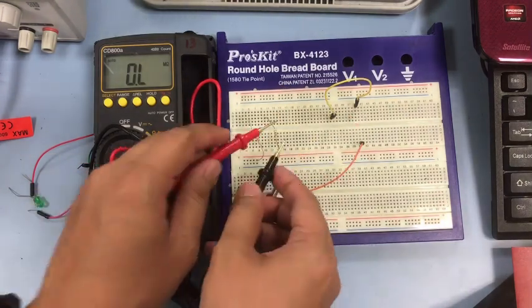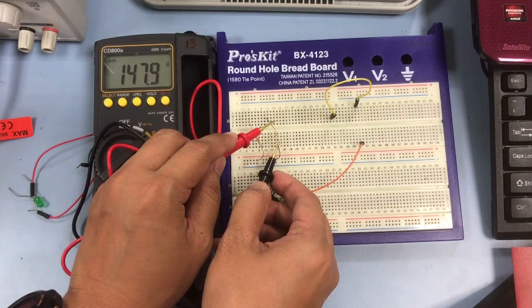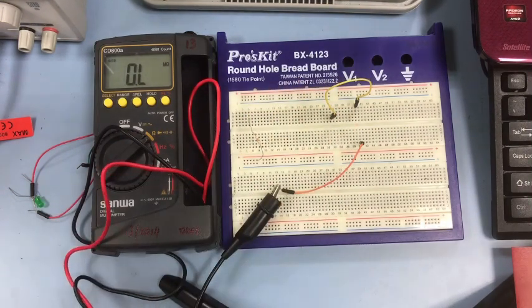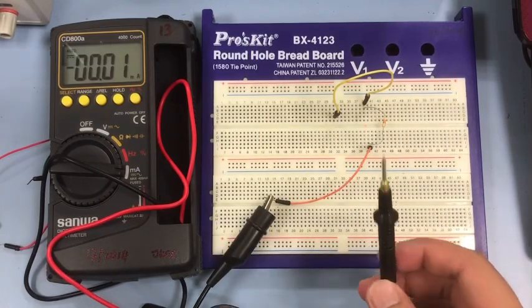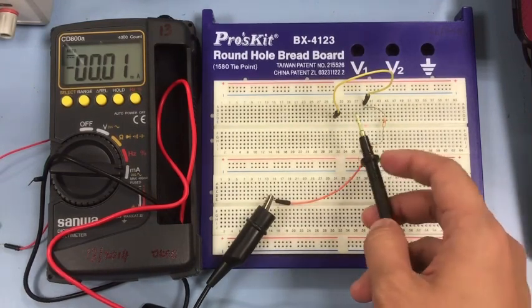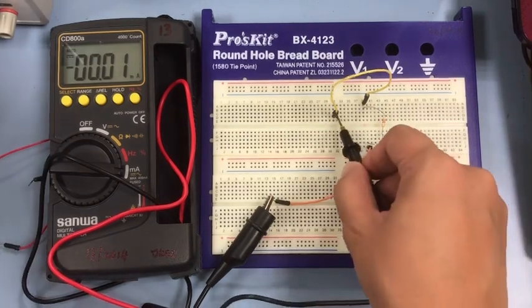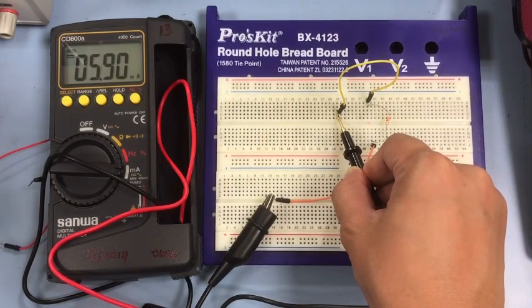Make sure you know the actual resistance so that you can do the discussion and know the reason why the actual data is different from the theoretical data. Now we want to measure the 330 ohm resistor, the actual one is 325 ohm, for table 1.1. Now we'll start with 2 volt. For 2 volt is 5.90.